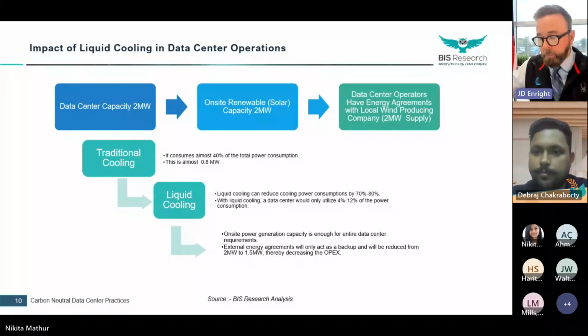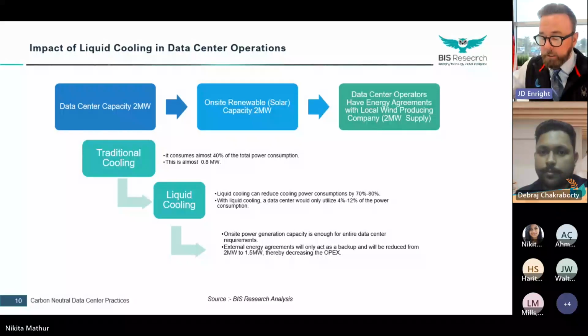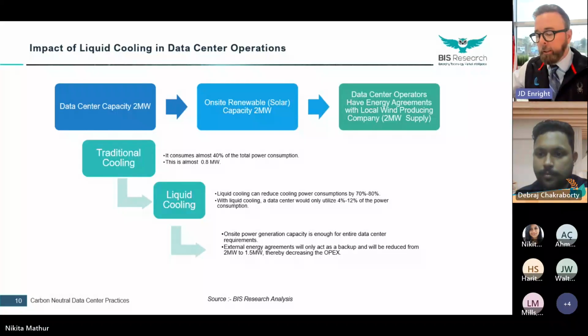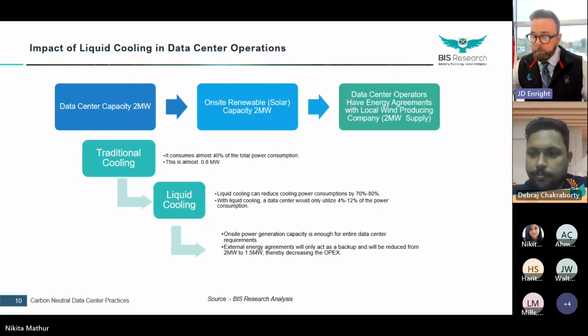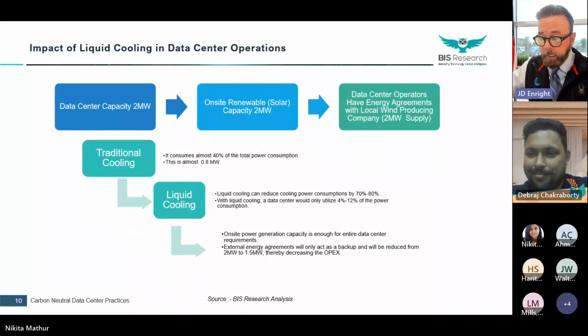Now, single phase fluids typically last about 5 to 7 years, depending on how hard you work them, that is, how dense the type of computing is. And if you know how to keep it clean and use fluid hygiene and not get materials in there, then they'll last quite a while. The beautiful thing is that some of them, not all of them, are fully biodegradable very quickly. So they add very little impact to the environment long term. And the process of manufacturing them is, in some cases, a byproduct of what's already being generated, which would normally go away. It's being reutilized, or repurposed, and that's great.